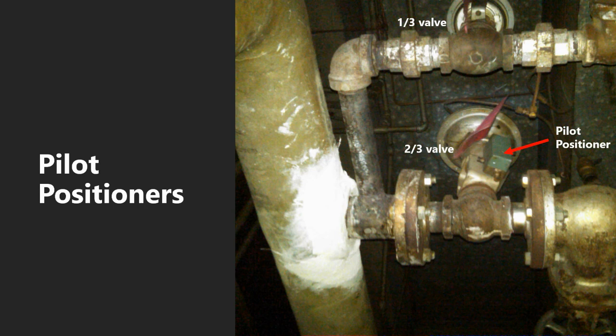Then a pilot positioner's second important function is to provide a higher volume air signal that many controllers are not designed to provide. This comes invaluable when operating larger valves with larger diaphragms. Using a pilot positioner can provide faster modulating action. And even more importantly to this discussion, they provide better ability to pinch off high pressure systems, as the larger size valve diaphragm will have mechanically greater closing force. And without the high volume capability of the pilot, the system will be slow to react, and particularly slow to react to any leakage that can be happening.